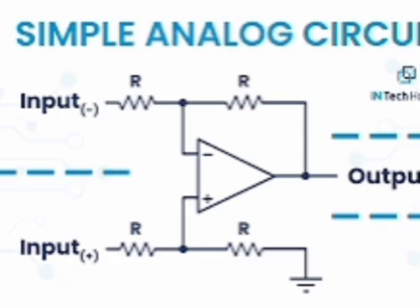Conduction angle for half wave rectifier theta equal to pi for ideal case. Theta equal to pi minus 2 sin inverse V gamma by VM, for the practical case. V gamma means cut-in voltage, VM means maximum voltage. Ripple frequency FR for half wave rectifier, FR equal to F, where F means input frequency.